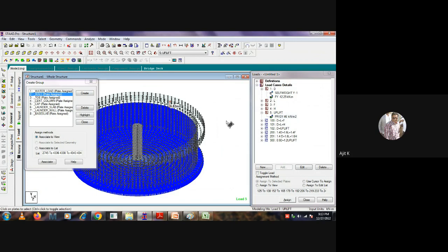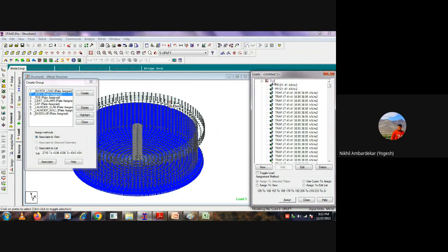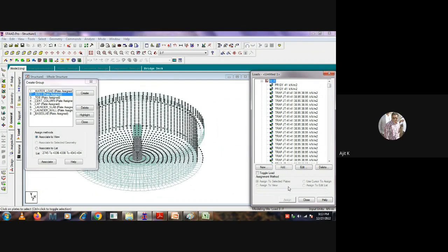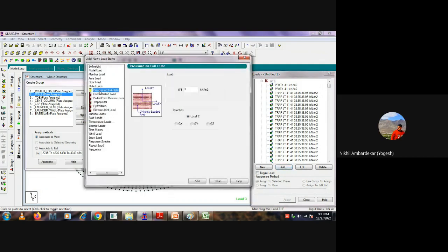Okay sir. So from just this example we can. Yes, just go to the fluid load. Yes. Add. Go to the plate load, full pressure, and I think water height is 5 meter, correct? Yes. So only minus 50 kilonewton you can apply to the water load plate. Yes. And same thing you can apply the soil load on the toe. Yes sir. Ideally it should be, and sir, we have to consider.